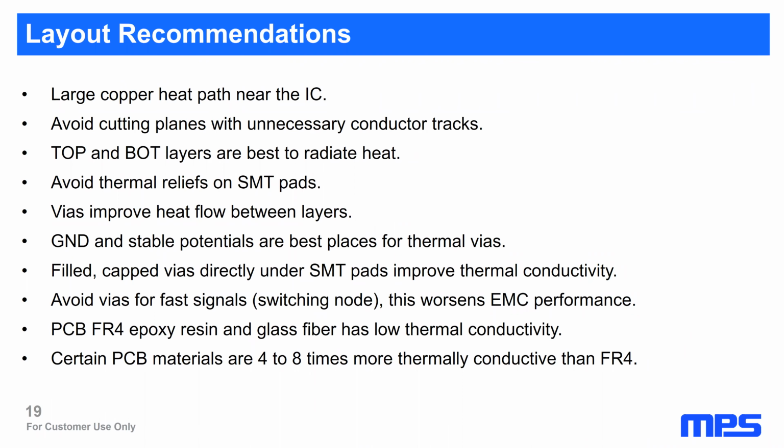GND and stable potentials are the best places for thermal vias. Filled and capped vias directly under SMT pads improve the thermal conductivity. Of course, if the via is directly under the pad, it's perfect to transfer the heat directly from the pin into the PCB, to the inner layers and to the bottom layer. But of course, that technology costs more money if the via has to be filled and capped with copper. It depends on the project if you have this margin for the price.